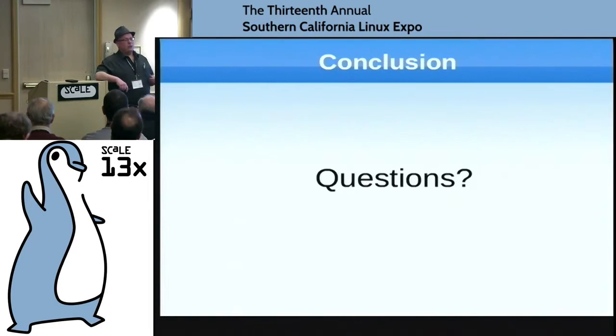Oh yeah, this is good, but your ground plane is not necessarily as big as it should be, or you've got this labeled incorrectly. Just simply providing feedback, just like somebody would submit a patch to a mailing list. If you're on the mailing list and you can give them some advice to make their design a little bit better, that's very important. Actually, for the hardware review, it's extremely important because mistakes are extremely expensive.